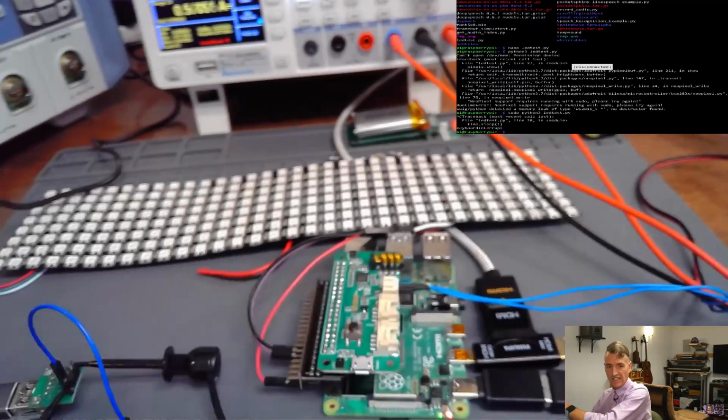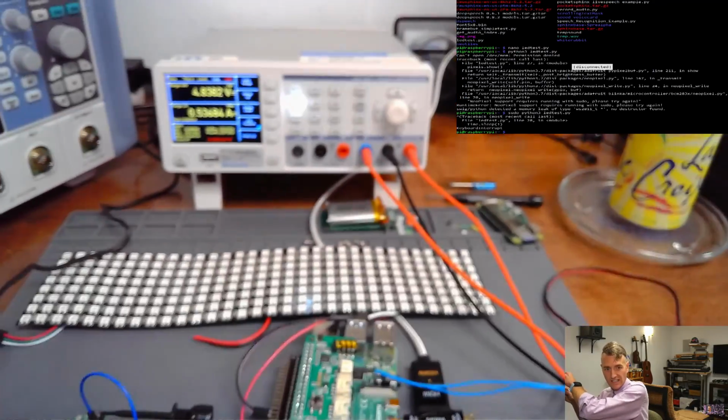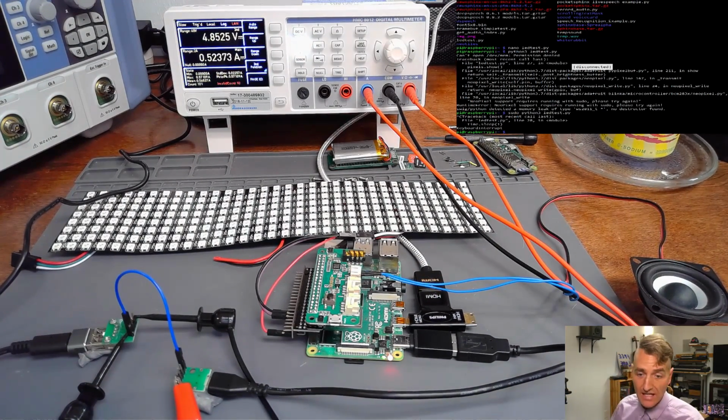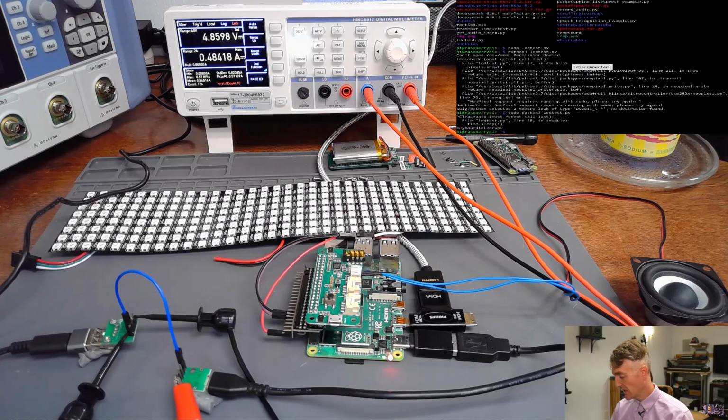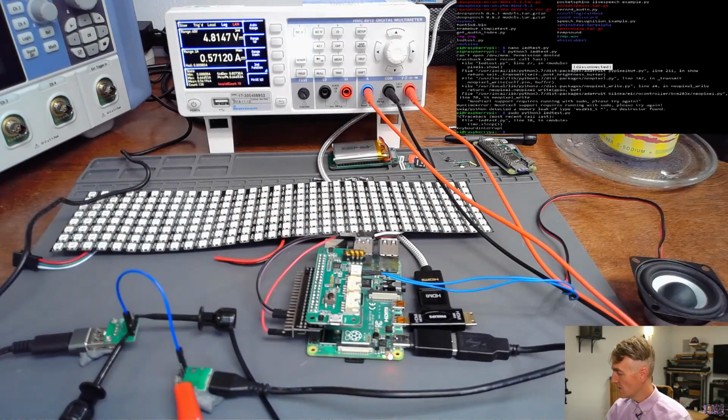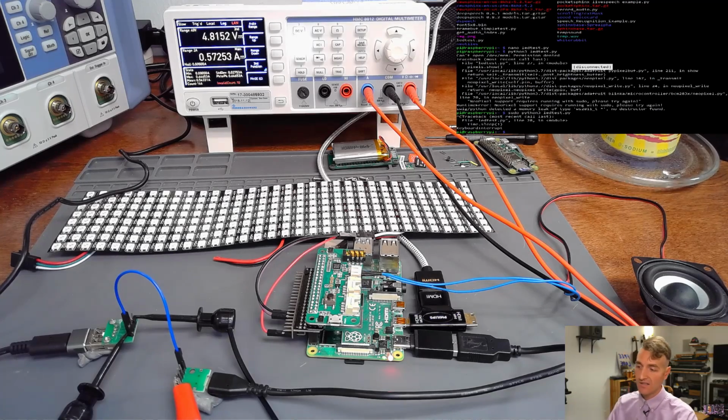So I guess I'll have to read the tiny script for you. If I could ever figure out how to get that DMM's output onto the screen, that will be awesome. But so far, I have not figured that out. Before, the Raspberry Pi Zero was using 220 milliamps, and the audio board was using 30 milliamps. Now the Raspberry Pi Zero and the audio board are plugged together. So, oh my goodness, it's occasionally jumping up to 646 milliamps. So the Raspberry Pi 4 is using about 3 times the current of the Raspberry Pi Zero, just chilling out.